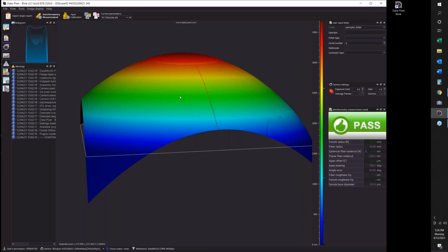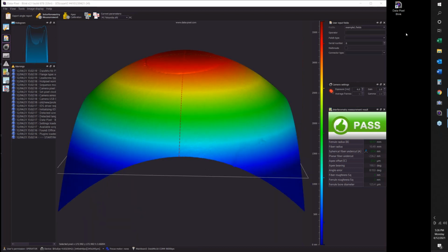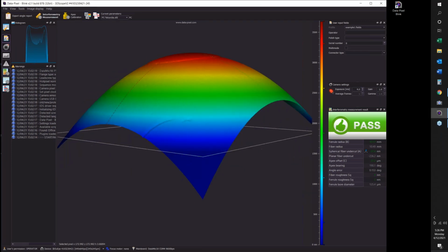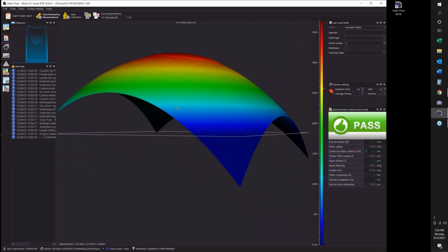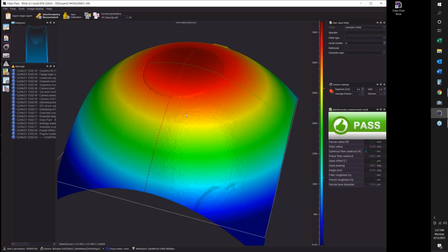So a good source of quick diagnostic is a laser pin, 650 nanometer, to show you whether or not you have dirt buildup or your contact is basically broken. The contact has been damaged by repeated use mates or by another contact that was improperly polished. You don't need to own one of these. It's imperative that we own one to proof the polishing technique meets the Telecordia standard. But I think it's a unique thing to show you, as you're never really going to see one again unless you get into the industry of polishing fiber contacts and meeting manufacturer standards.